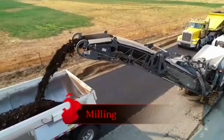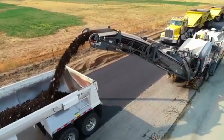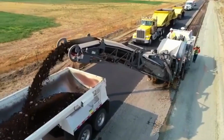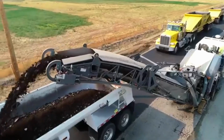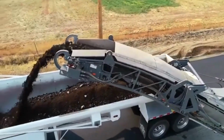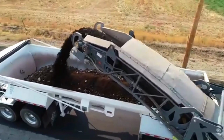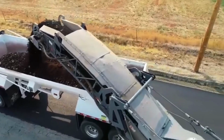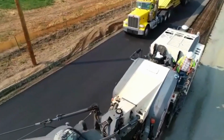Step 2. Milling, if required. In many cases, the old pavement is milled before placing the new asphalt layer. Milling removes the damaged surface to create a smooth and even base. It maintains curb and drainage levels, preventing water pooling. The milled asphalt is recycled, making the process environmentally friendly. Milling depth depends on the severity of damage, typically ranging from 25 mm to 100 mm, 1 to 4 inches.